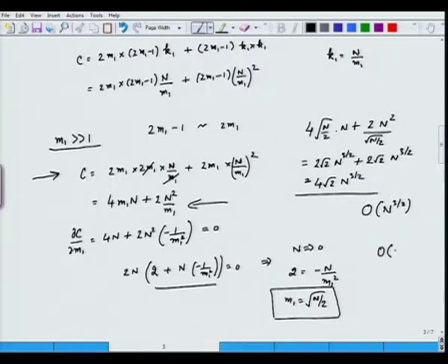So, we have now been able to go from n square to a lower complexity than what we had in a single crossbar. So, I am able to reduce my number of cross points. Of course, the only thing is that now I have introduced complexity in terms of the routing algorithm, which is required because you have to search for a path and then you have to set up a path, but a path can always be set up. So, this is a pretty efficient system.